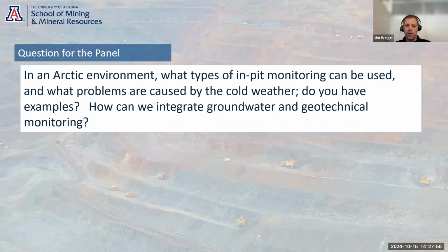In terms of integrating groundwater modeling and geotech monitoring, we'll put two, sometimes three piezos on an inclinometer pipe when we grout them in. Similar with the shape arrays, not a problem when you're actually constructing the hole. And then most of our groundwater piezos also go in with TDR cables and all get grouted in. So we have fairly good integration in terms of geotech and hydro here at Kennecott.